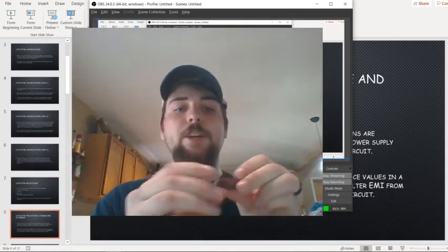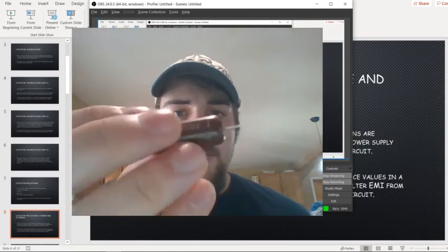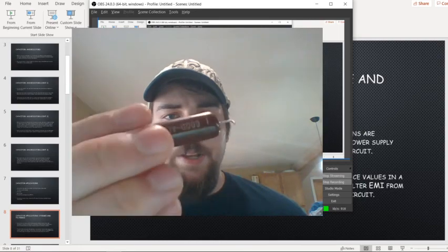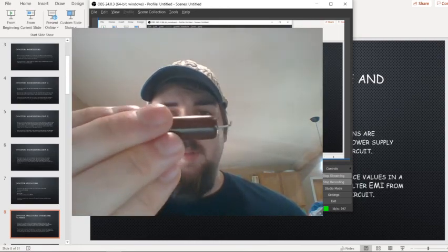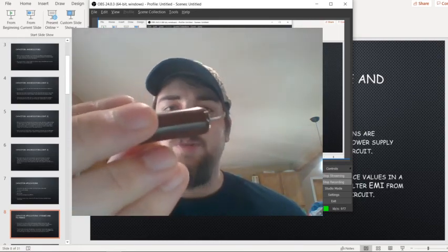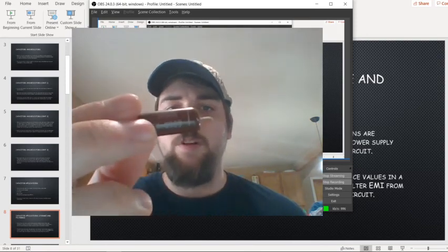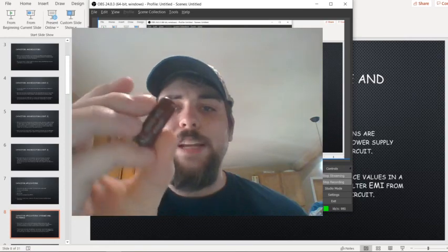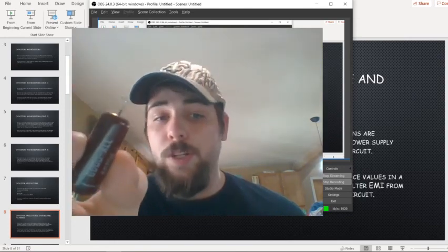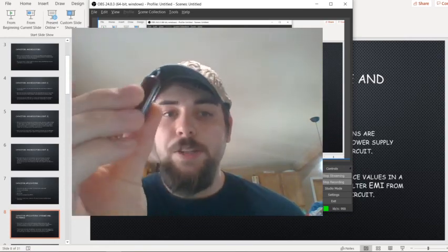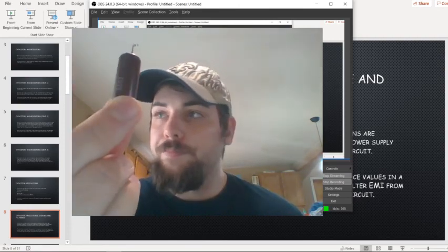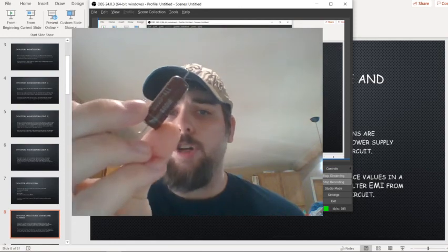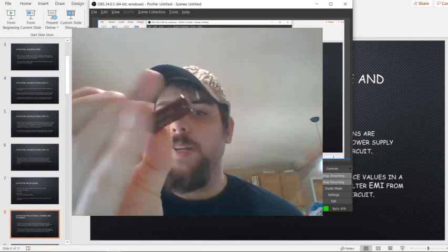Right, like this one. This is a Goodall capacitor, and it's a 0.1 microfarad capacitor, plus or minus 20% tolerance, 400 volts DC. Now, the reason why I took this component out is because this is what's known as a paper capacitor, and it has a very high leakage current because of its age.